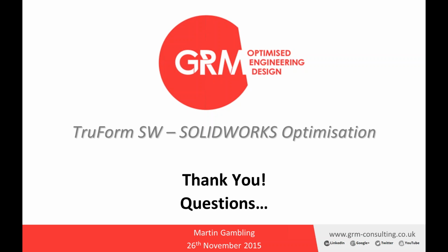If you're not aware, you can save an assembly as a single part in SolidWorks. So if you're having any issues optimizing an assembly, save it as a part, remembering to check the option to save all components into that part. And that will allow you then to perform the optimization on a sort of multi-body assembly.